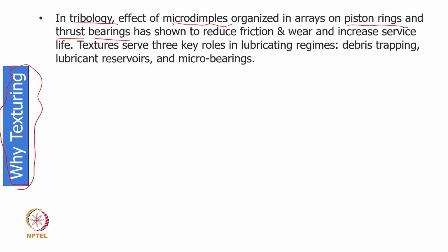Basically the micro dimples, which we showed in the previous slide also, organized in a structured manner, in matrix or array form, really reduce the friction, reduce the wear and increase the surface life. Sometimes we were talking initially of only a 5000 hours cycle life, now we talk about 50,000 or 15,000 cycle life also, just by tuning the surface, and that is the beauty of surface engineering.